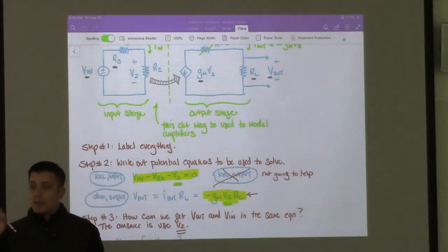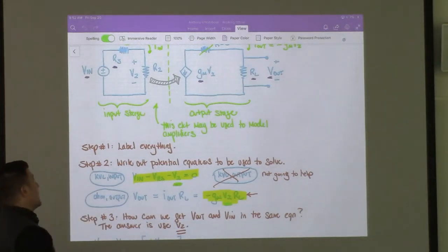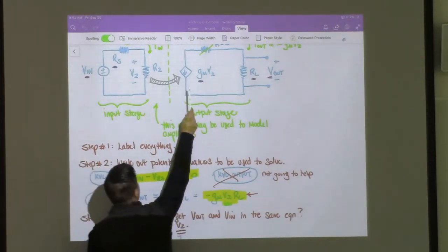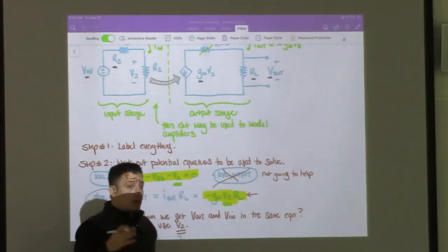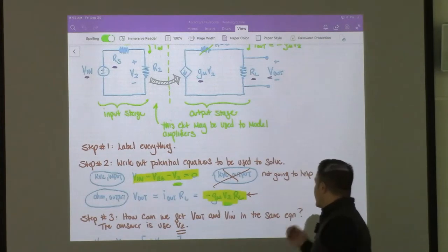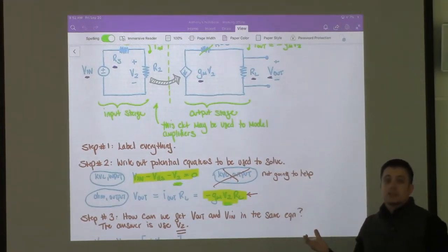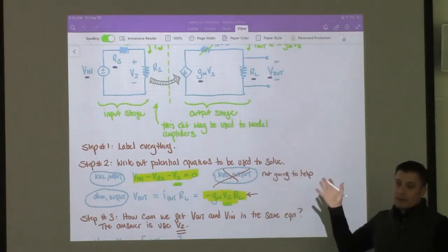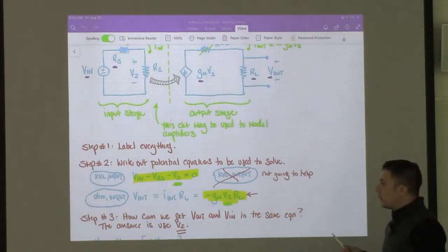For a voltage source, voltage is known, current is unknown, and vice versa. I could make up a name and say the voltage across this source is called Vx, and then write out the equation, but it's essentially going to be just introducing more unknowns into it. So you could have written it out, but it ultimately is not going to help.